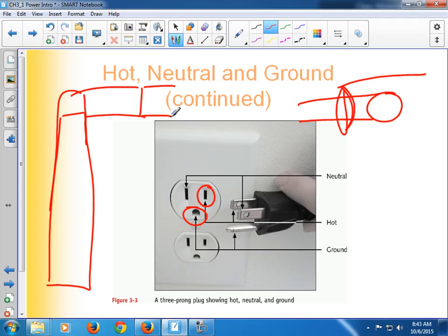Because this ground is the most important thing when it comes to plugging in electrical stuff for us. Okay? Because without a good ground, no surge protector works, no backup power supply works correctly. Okay? So you have to have grounded outlets for that to happen. And in my church, half the outlets aren't grounded at all. They're 2-prong outlets. And if you see just a 2-prong outlet like that, it's old.